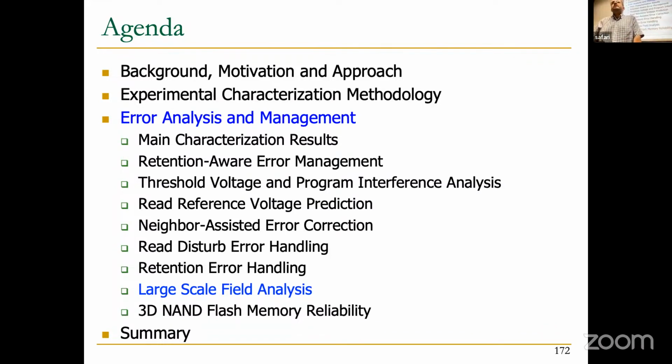The question is about fast and slow leaking cells: where do we store the characterization? Actually, we don't need to store it in the SSD. You can store it somewhere else. We are doing this process when your device is dead, when your device is not recoverable, and we want to recover it. So we don't have that kind of storage overhead.